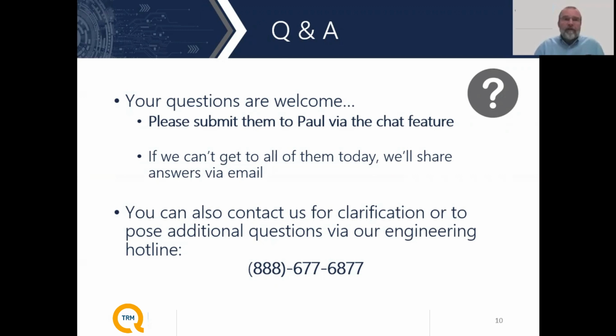Absolutely. I think if you're looking for a part that is going to mount, for example, on a PCB as part of an internal component that's going to be part of a subsystem, very often it's difficult to get connectors into that system, and that would lead us into a surface mount type component. Once you get into a surface mount type component, you really don't need or even want a metal housing around that component. So that kind of drives you into either a bonded multi-layer sort of component, or if you're talking about a low frequency broadband type of component, a PCB mounted sort of device